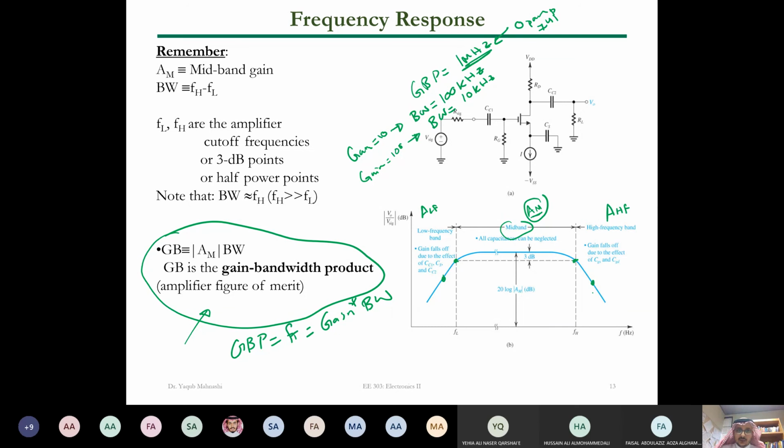So this is a measure that lets you know whether it is a good amplifier to get or to buy or not, like when someone buys anything on the market, it has features. So the gain bandwidth product is a very good measure, almost constant. And from there we can estimate the bandwidth of operation of our circuit based on the gain requirement of our application.